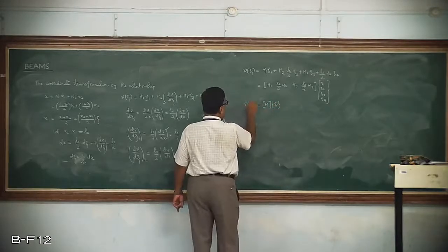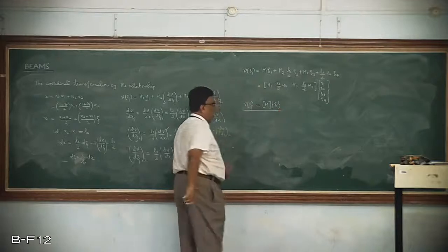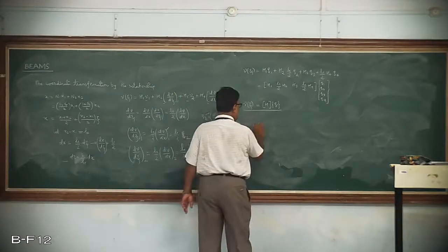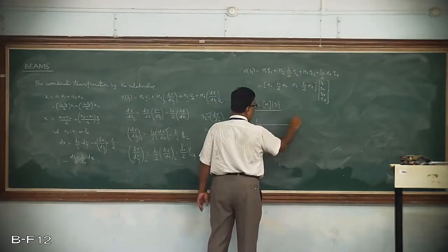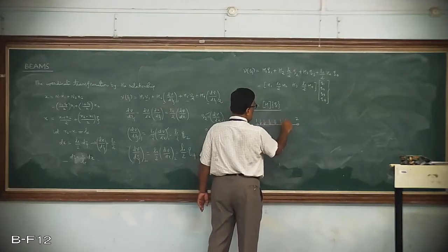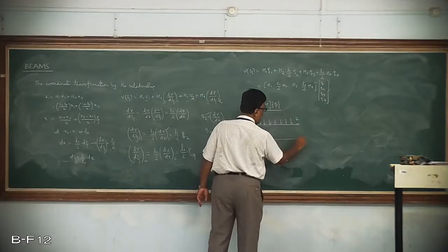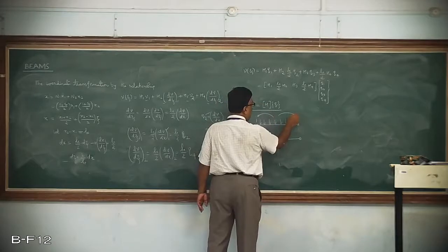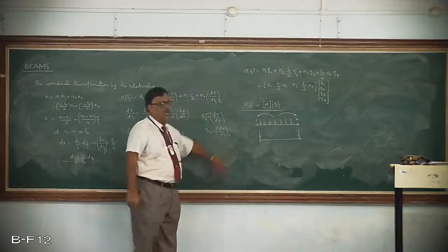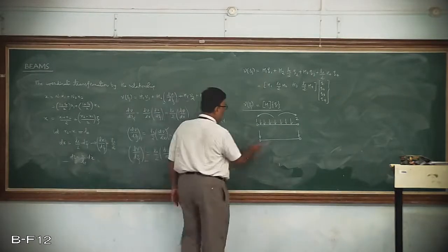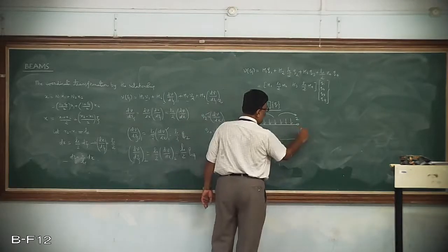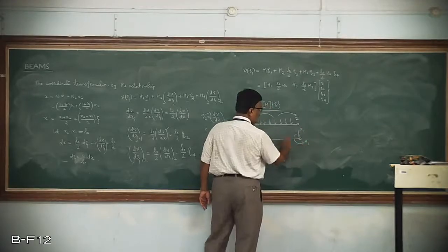Please remember, this is the deflection equation. So if you want to find out the deflection in an element, for example, if this is your element 1 and 2, subjected to some load, like let us say some UDL has been put on this. Always please remember, this UDL has to be converted into equivalent nodal loads. Nodal loads are in the form of one force and one moment. F1 and M1, and F2 and M2. What are the values of this? I will tell you later on.